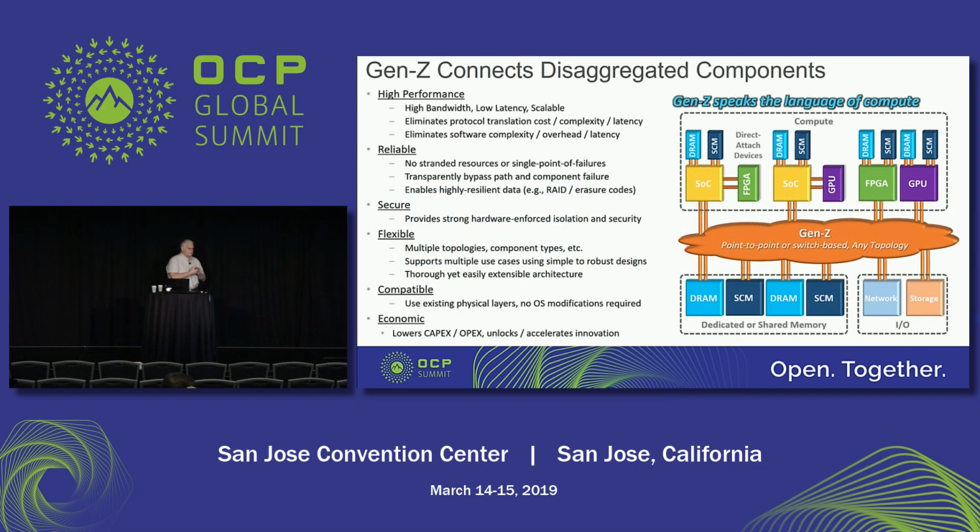It's high performance. We've been demonstrating stuff at 16 gig. We have two kinds of PHYs that we're talking about, PCIe-based PHYs and 802.3 PHYs. Our PHY group is specifying all the way up to 112 gig transfers at PAM4.